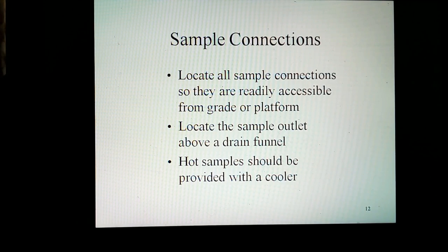Sample connections. Locate all sample connections so they are readily accessible from grade or platform. In general, when liquid samples are taken in a bottle, locate the sample outlet above the drain funnel to permit free running of the liquid before sampling. Hot samples should be provided with a cooler.